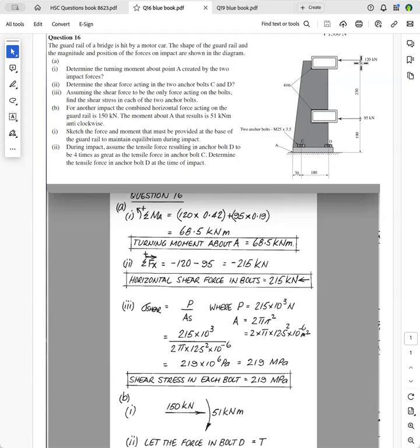What we've got here are sections called RHS, rectangular hollow section, and this is a low carbon mild steel plate. These are made from low carbon steel, with a carbon content of less than 0.3%, around about 0.1%, and we did this with introduction to heat treatment last week.